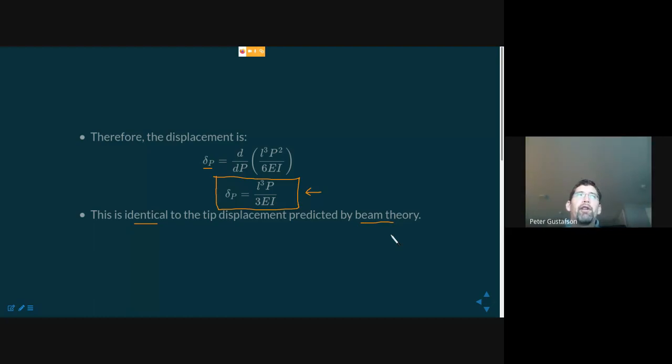If you're Burt Rutan, and you want to know whether the Voyager is going to have a wingtip strike as it rolls down the runway, and it did. If you wanted to avoid that and you wanted to estimate what the tip deflection was, because that's the first place that's going to hit the runway, you could use this method to fairly quickly estimate whether that would occur.